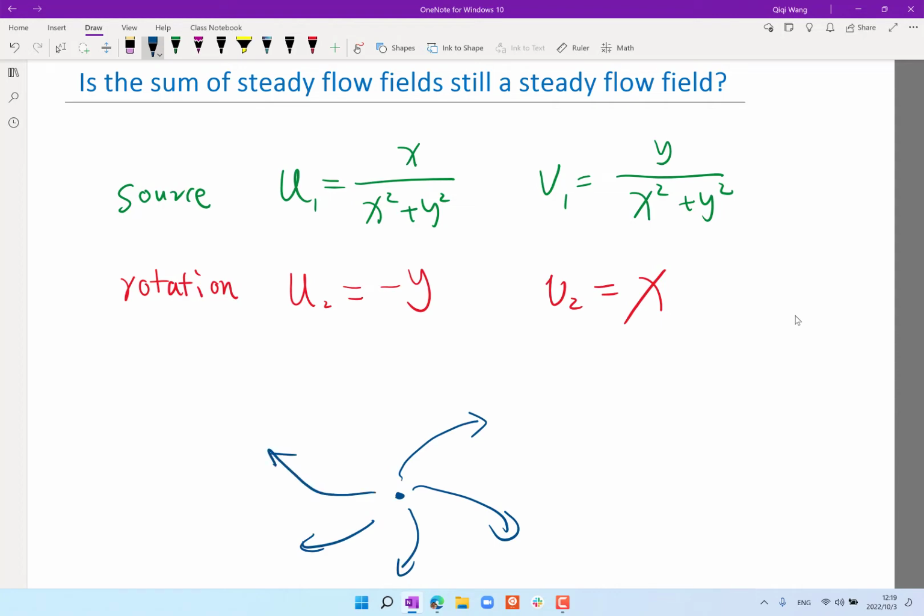And as the flow goes towards higher and higher radius, it automatically gains more angular momentum just out of magic. All right, and the pressure force is a conservative force because it's proportional to the gradient, right? So it cannot provide a torque to the flow field.